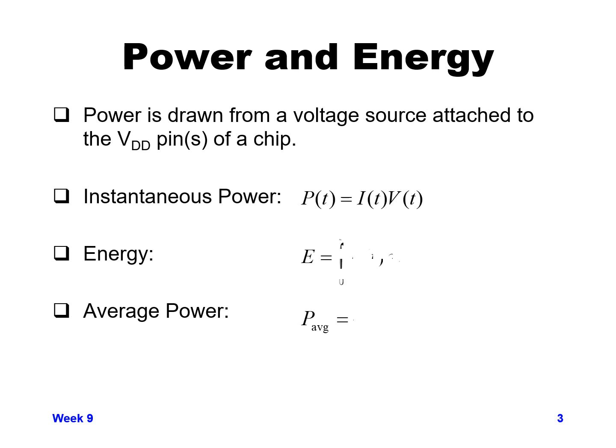Now your energy is the integral of your power over a certain length of time. The length of time that we're talking about here is capital T, and so you take your power value for each instant in time and integrate that power value over the period of time from 0 to capital T, number of seconds, milliseconds, microseconds in time.